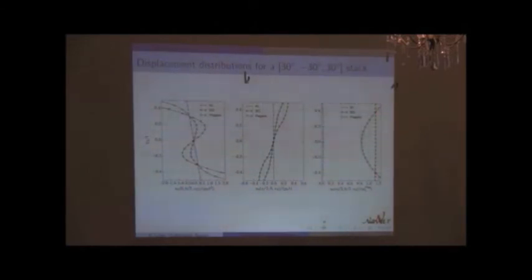Again, we start with slenderness 1. So it is not very surprising that Kirchhoff-Love is very, very poor in this situation. And if I make the plate slender, it is converging, and you see that Kirchhoff-Love is painfully trying to reach the exact solution, and even at 20 we are not very good.